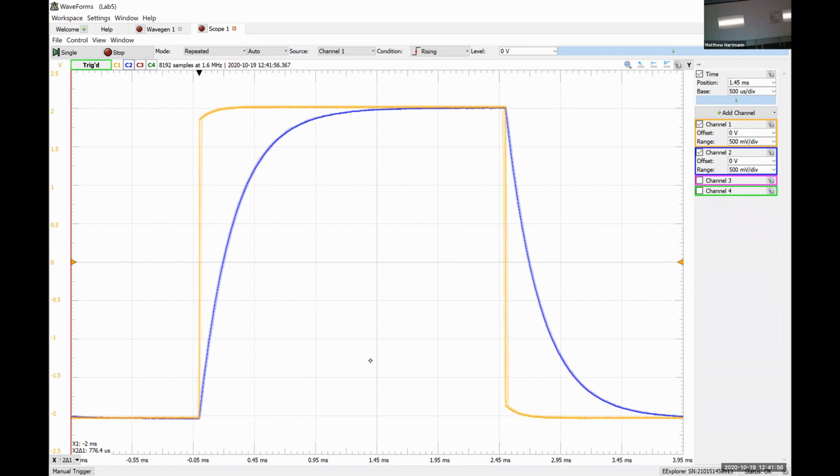So we can look at this graph pretty easily and figure out what B is, right? What's it going to be? 2 volts, exactly right. What does the quantity A represent? Y at 0 plus minus y at infinity. So it's that first term, the coefficient of our exponential response.